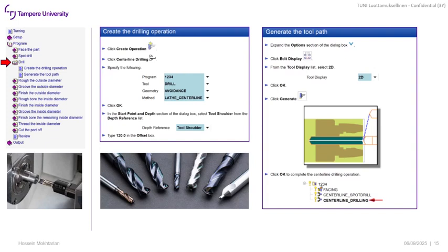And of course, another thing that we need to consider is, based on the surface roughness specification of our drawing, do we reach the final surface by only drilling, or do we need to leave a little bit of material to do the finishing in the drill hole area? If there aren't any specifications or the intended surface is rough enough, then we can perhaps go with only drilling, as we are doing here with only a drill with a diameter of 20. We're going to finish it all.